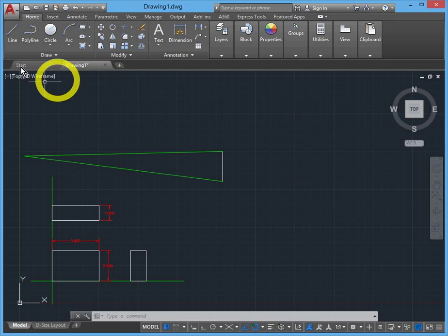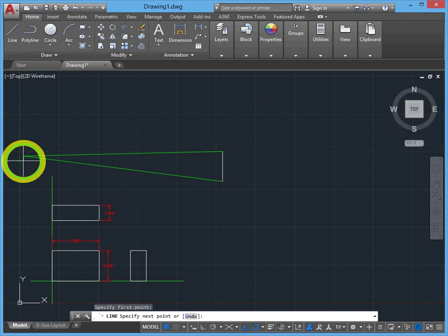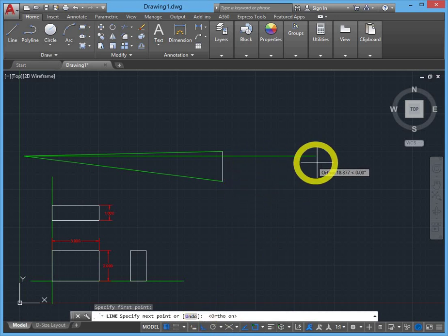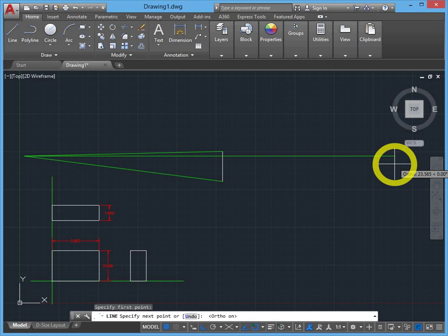In architectural graphics, I would want my 2 vanishing points to be absolutely horizontal. And so I would turn on ortho mode, and I would come across to some other point, and I would pick my second vanishing point. So that would be how I would do this in architectural version of 2-point perspective.